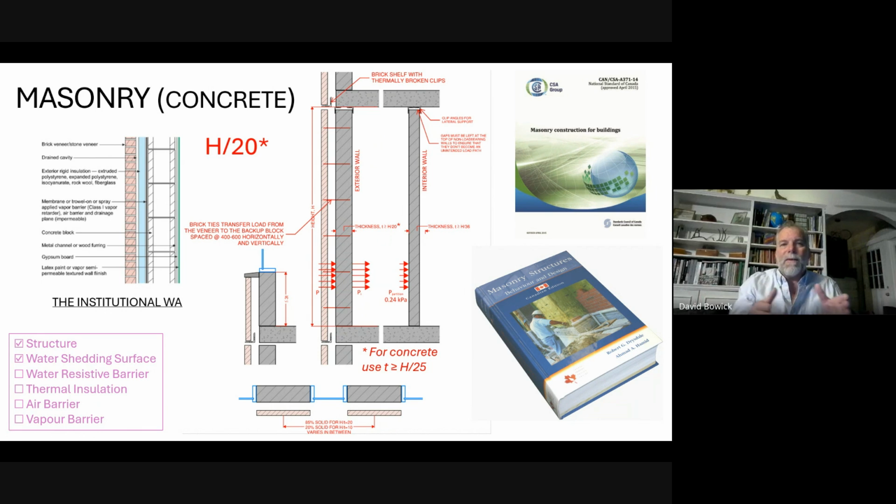So what does 20% solid look like? Well, let's say that you have a 4 meter wide window every 5 meters. So if you cut a plan section, you have a meter of solid, 5 meters of window, a meter of solid, 5 meters of window. That would be considered 20% solid. 1 meter out of 5 is solid.